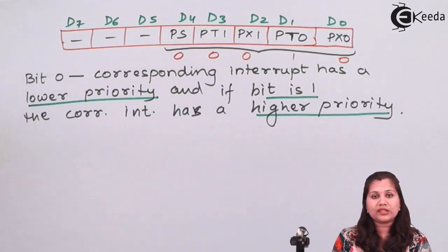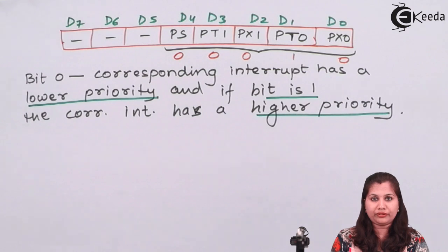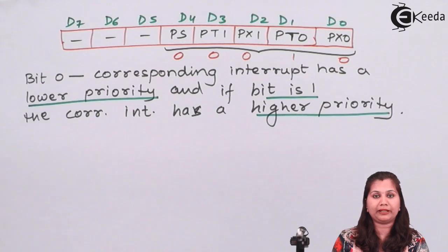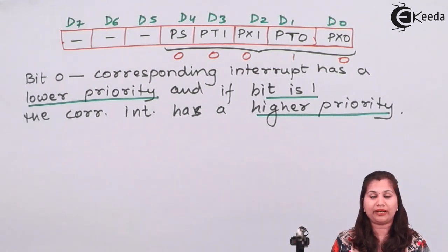Okay, so in this video we studied what an interrupt is, how interrupts are classified, and what steps are taken by the microcontroller whenever an interrupt is given to it by the peripheral devices. Then we studied the types of interrupts in 8051; we have 5 interrupts in the 8051 microcontroller. Then we studied the 2 registers IP and IE, which are used to deal with the interrupt structure in 8051. So I hope that this topic, interrupts in the 8051 microcontroller, is clear to you. Thank you.